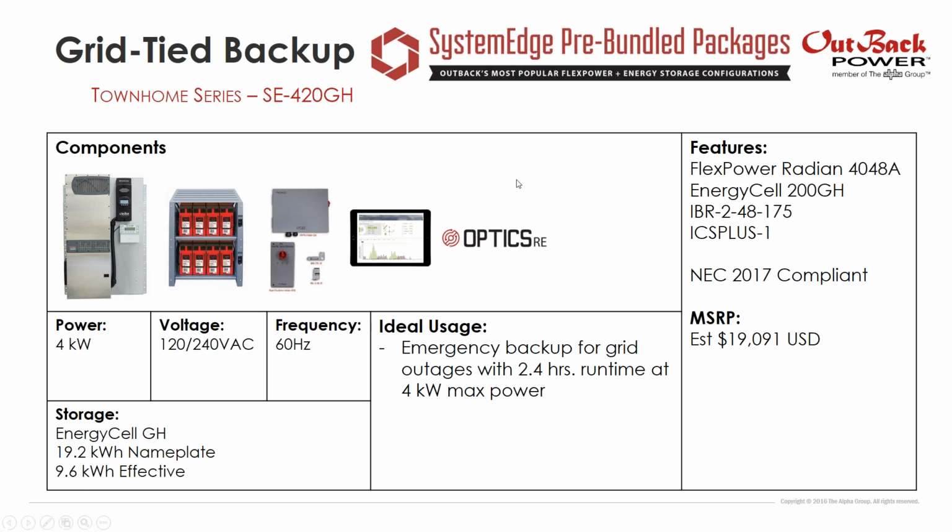It pairs up with 20 kilowatt hours of nameplate storage, which you can actually get more than 10 kilowatt hours out of. In a backup application, you can take these batteries to a deeper depth of discharge. We recommend 70 to 80% is acceptable in a battery backup application where you're having maybe a half dozen power outages in the course of a year. It's okay to hit those batteries pretty hard in that case.